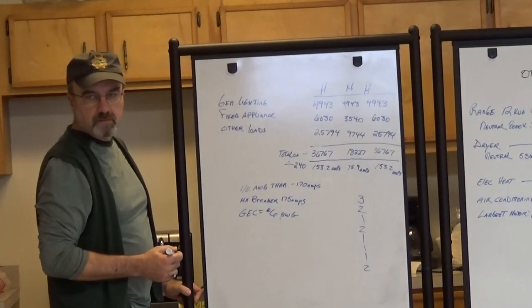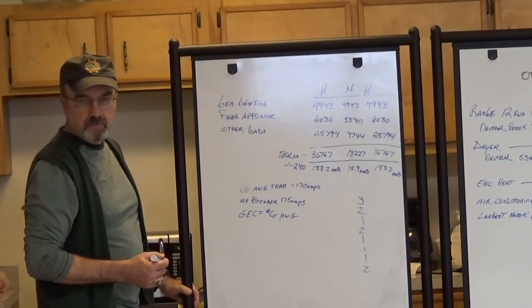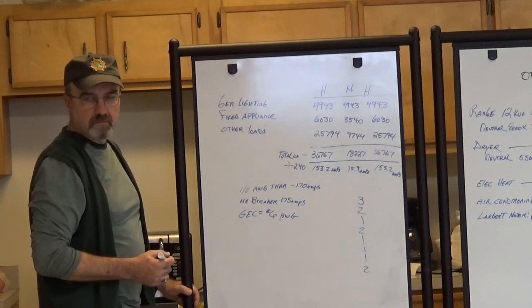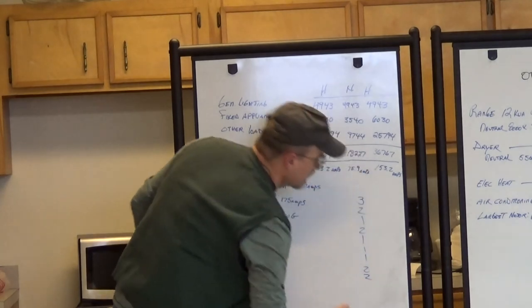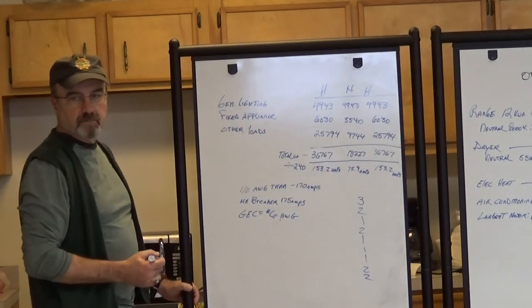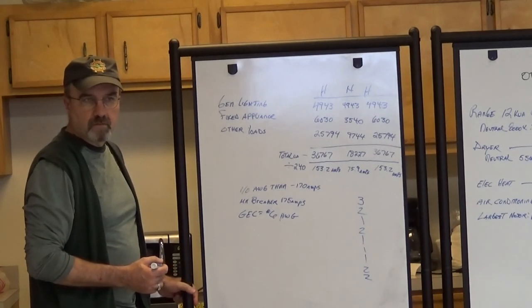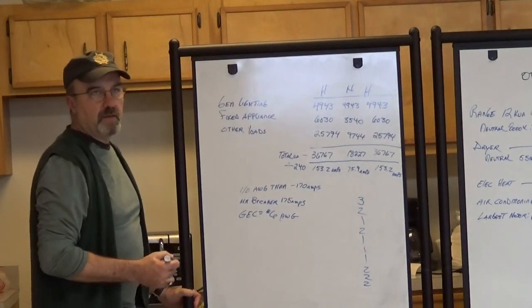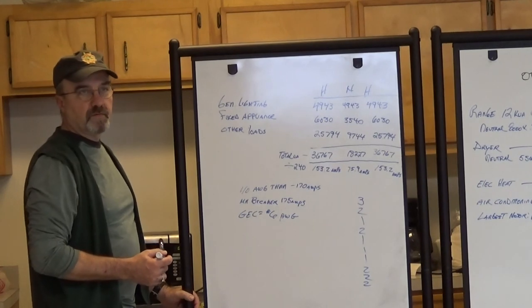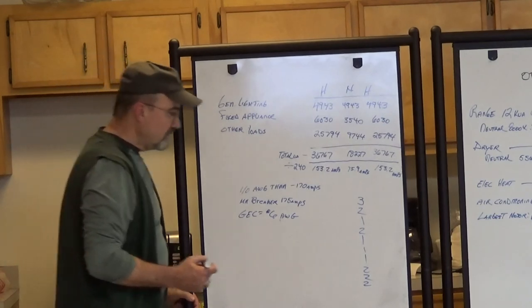What else do we have? Electric dryer. What voltage is that? 120. Why? Oh wait, it's 240. So two spaces in the panel board for that. Electric heat, at what voltage level? 240, so two for those. And we have to run an air conditioning circuit for the air conditioner unit, 240.